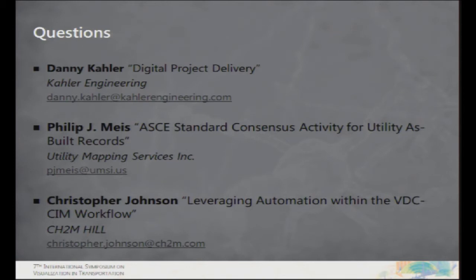And now very good is taken with a grain of salt when we're talking about utilities here, but assumptions such as, okay, even if you look at the as-built and it says it's X deep, I'll tell you, Chris, right now it's going to be between 42 and 46 inches deep, and this is 2-inch conduit. So it was basically a spreadsheet that lists out by utility type what the depth of it was, what the size of it was, and then in the case of a three-dimensional item like a light pole, whether it had a 2D analog, which was like a single or a twin light pole, and there was a 3D block cell developed that just mapped it.